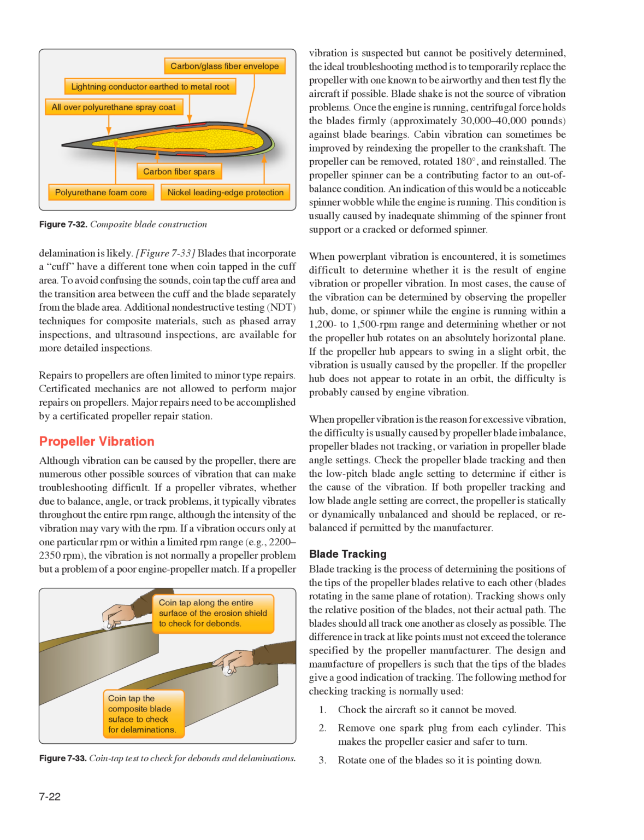Additional non-destructive testing, NDT, techniques for composite materials, such as phased array inspections and ultrasound inspections, are available for more detailed inspections. Repairs to propellers are often limited to minor type repairs. Certificated mechanics are not allowed to perform major repairs on propellers. Major repairs need to be accomplished by a certificated propeller repair station. Propeller vibration.